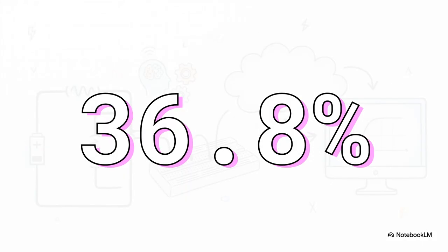But there's a flip side to this. At the exact same time that charge is building up and pushing back against the power source, the current flowing through the circuit is dropping. At that exact timestamp of 1 tau, the current falls to roughly 36.8% of its starting value. So charge goes up, current goes down. It's this perfectly balanced, complementary dance.